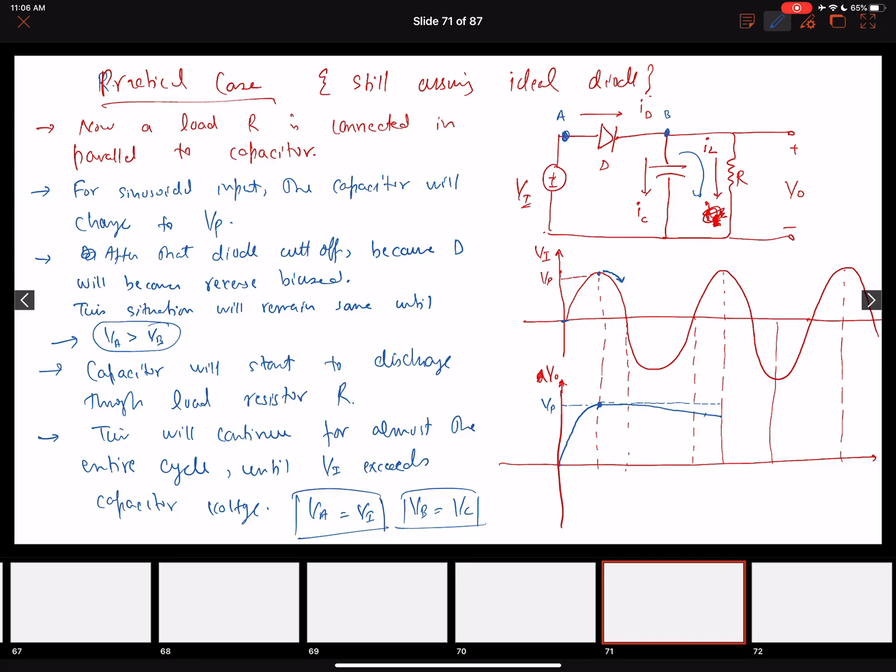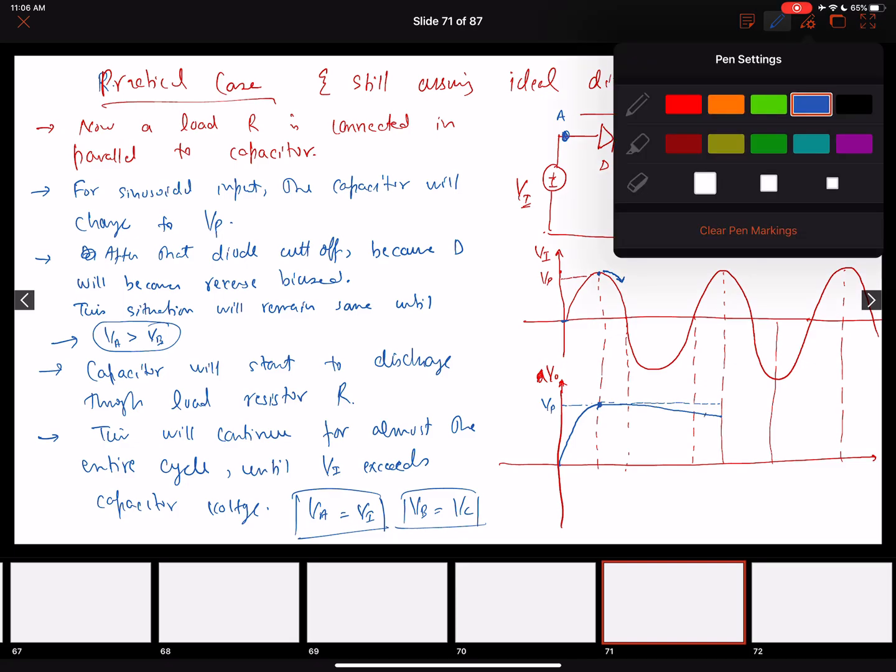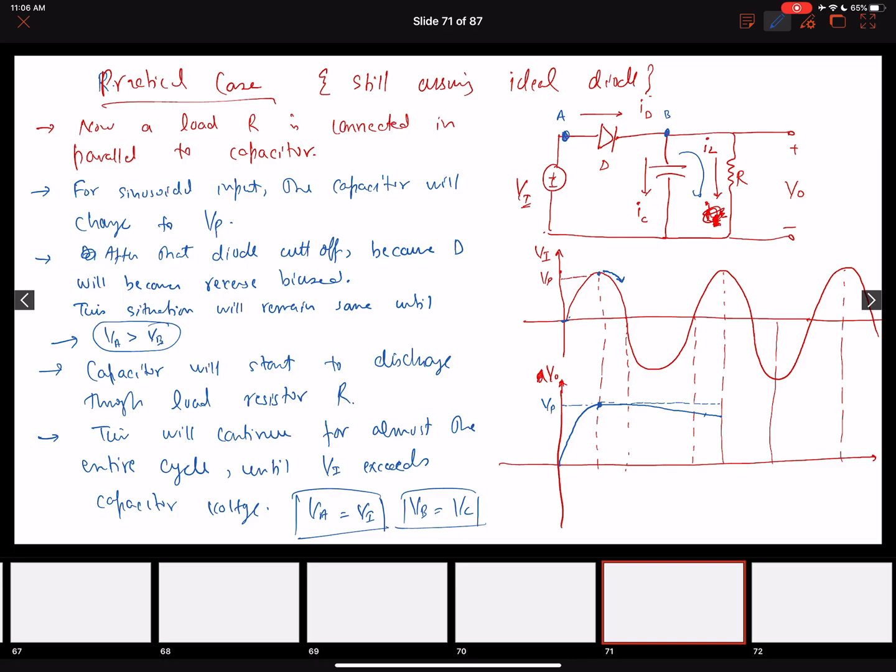Yeah. So let me draw this output essentially. On this waveform, it will probably be a little easier. Okay. So it will charge over here, then it will start to discharge, and it is going to continue to discharge until almost this point. And now what will happen at this point? At this point, this is my voltage across a capacitor, right? So this is V naught.